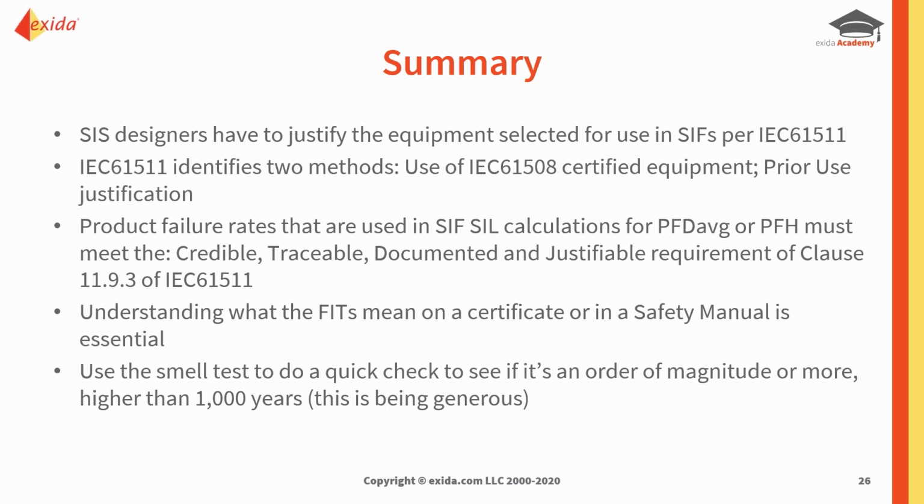Because I like the equipment, it doesn't count. Product failure rates that are used in these SIF SIL calculations for our PFD average or our PFH must meet this credible, traceable, documented, and justifiable requirement. And if it doesn't, then it's not going to be compliant.